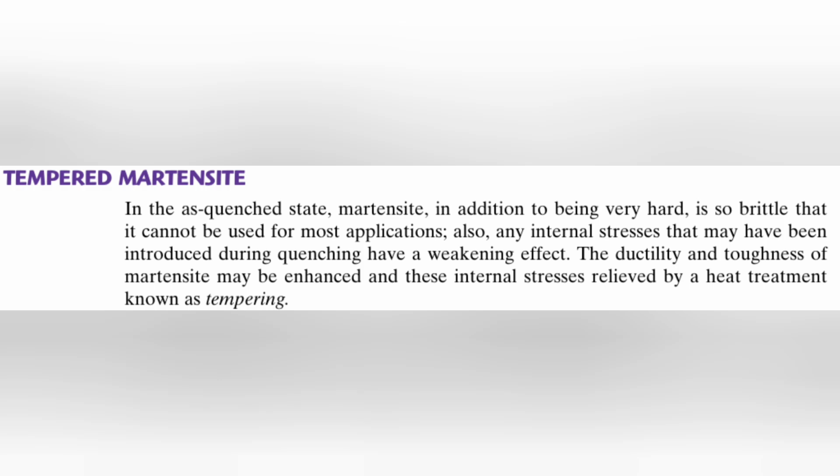Suppose here we know martensite is suddenly formed due to sudden quenching. So obviously it will become harder, but on the other hand it will be brittle and weak. So it could suddenly break. That's what that sentence is explaining. So that rapid quenching will have a weakening effect. So ductility and toughness of the martensite may be enhanced, and these internal stresses relieved by heat treatment known as